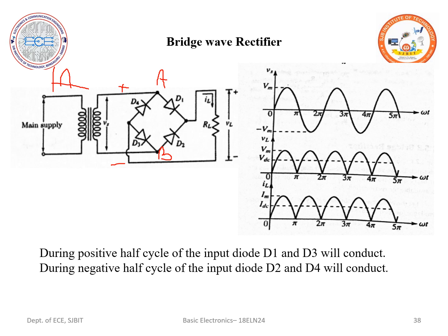Now look into D3. My cathode is connected to the negative terminal, so I can say my D3 is forward biased. So my diodes D1 and D3 are forward biased, whereas my diodes D2 and D4 are reverse biased. So I can say during the positive half cycle, my diodes D1 and D3 are on and my diodes D4 and D2 are off.